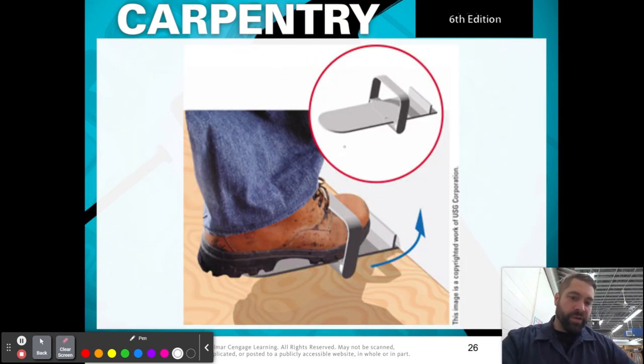Here's what a drywall lifting hook looks like. So in this instance, these look like maybe they're Tim's, I can't tell. But this just slides right in, put your foot down on it, and it raises it up just enough to come in contact with the other panel and give you a nice gap underneath.